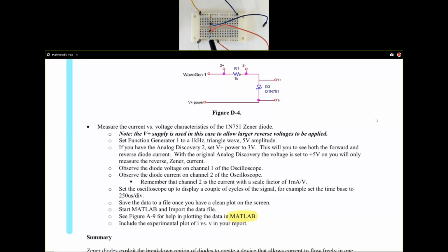So we have the Zener diode. The positive is pointing up. The cathode with the black ring is pointing down, connected to this bottom rail where I am going to supply power. Instead of white, maybe a red wire is going to be better for this because we are connecting it to the positive supply.